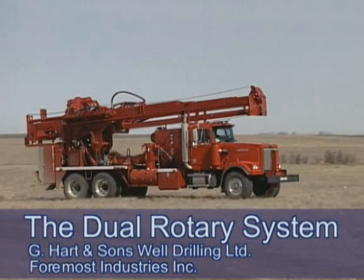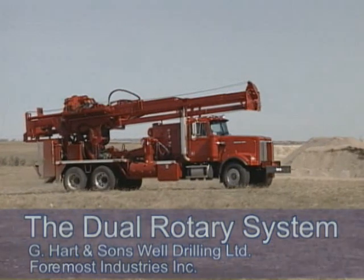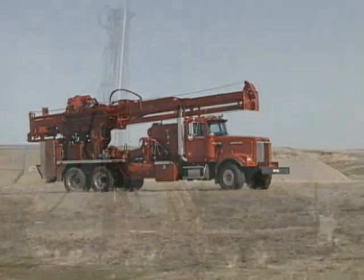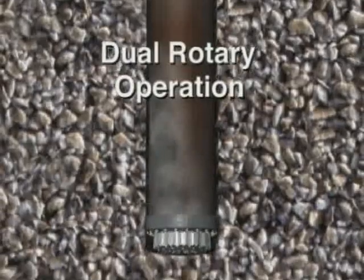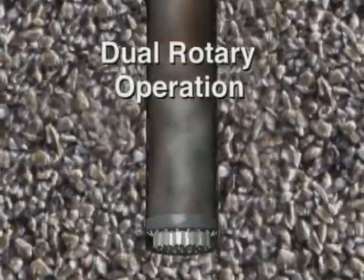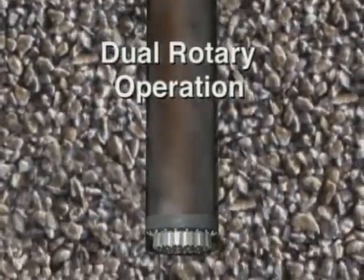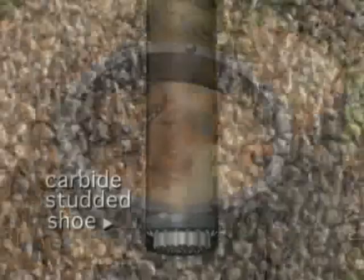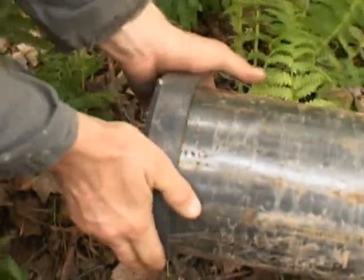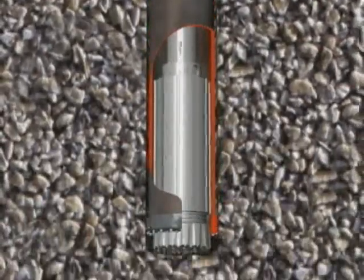The dual rotary drilling system represents one of the more recent advancements in drilling system technology, being especially well suited for drilling in unconsolidated material, such as overburden, glacial till, cobbles, and gravel. As the name implies, the dual rotary system utilizes 2 heads to simultaneously advance the hole and the casing. A lower rotary drive rotates and advances casing, while a carbide shoe enables the casing to cut its way through the formation. The top head drive drills inside and ahead of the casing.